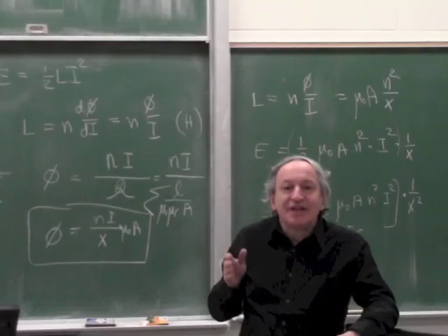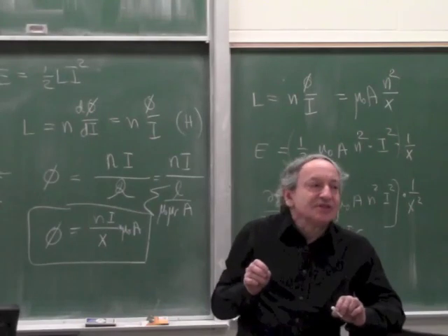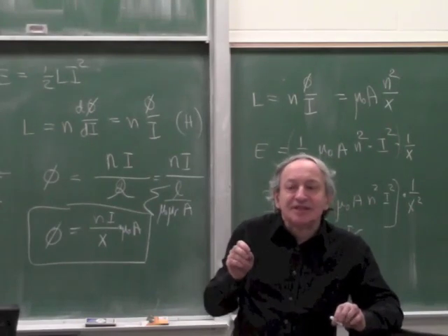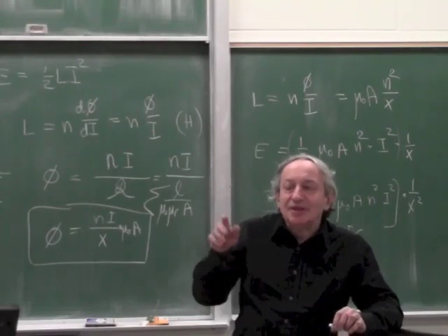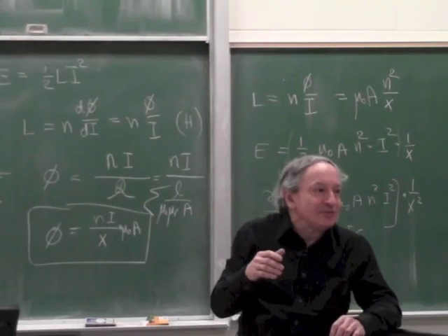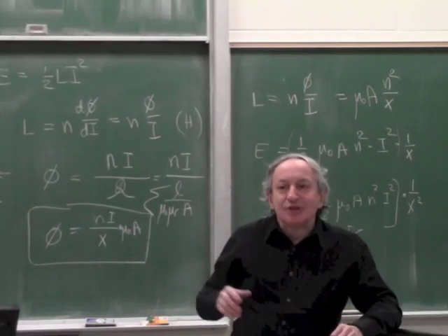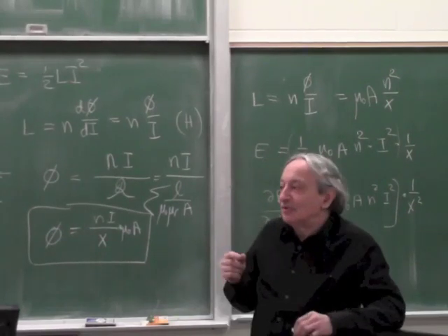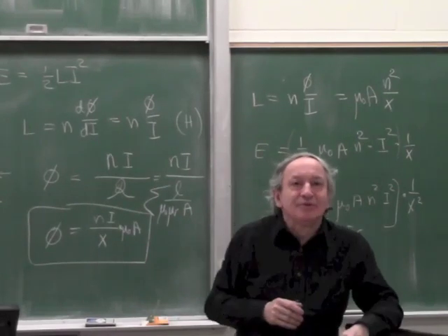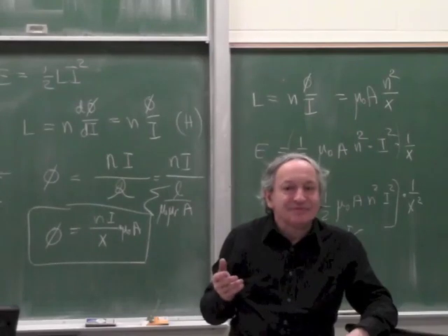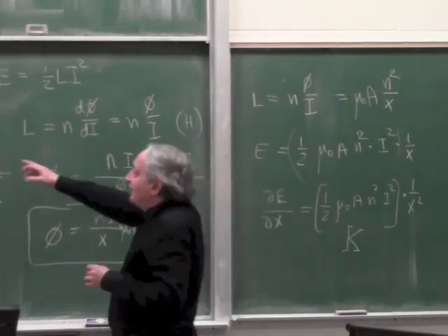So when you have a fixed gain servo system, like a moving coil actuator, you fine-tune the system so that you just reach stability, but you maximize the gain you could. You look at the peaking, you look at the phase shift, you say, okay, I can add a bit of gain because I still don't have a 180 degree phase shift, so you maximize the operation. But here you have to do this fine-tuning for the highest gain, and at any other position of the actuator there will be lower gain, and the system will work poorly. Is that clear? Good. So that's the problem with systems with variable gain in servo.